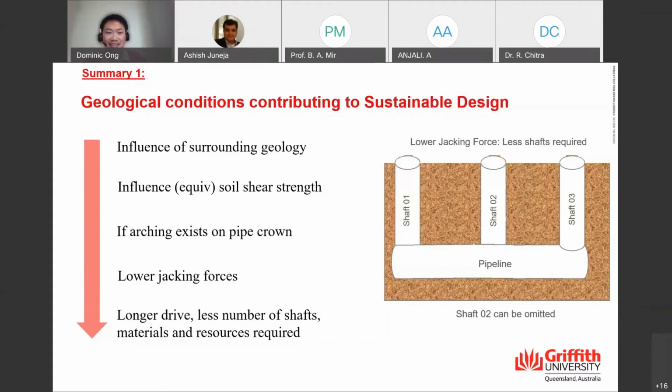Okay, you have to do it very well, because if your pipe resistance exceeds your hydraulic jack capacity, that's where the problem will come. If you do not predict it well, then your hydraulic jacks reach the maximum capacity, and your pipeline hasn't gone out to the retrieval shaft. That's where the problem is. Then you have to come with a rescue shaft to sink and rescue your tunnel boring machine. So that is a double-edged sword. You have to be very confident with what you do.